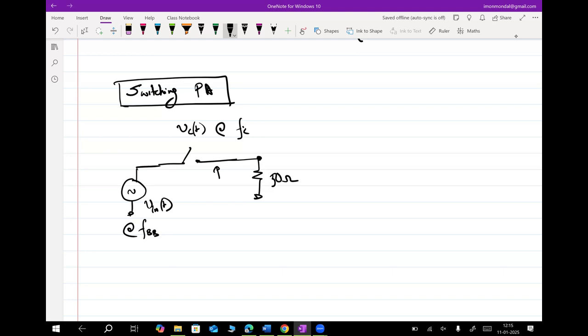Now, the issue is you never have signals with pristine voltage sources, because a pristine voltage source can deliver infinite power. However small the amplitude is, a voltage source like this can deliver infinite power. I can ask for infinite current, and it is going to provide infinite current.